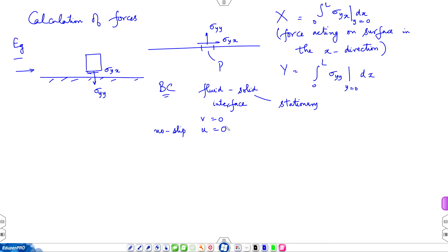Okay. So, you did some examples earlier where you saw a velocity variation. Away from the surface there was some flow, at the wall velocity came down to 0, which is the wall velocity. If the wall is given some motion like in Newton's parallel plate experiment, then the fluid particles are also dragged with the surface. So, there is no slip between them. Fluid velocity is equal to solid surface velocity. That is called a no slip condition, which is by and large observed in the type of applications we have dealt with.